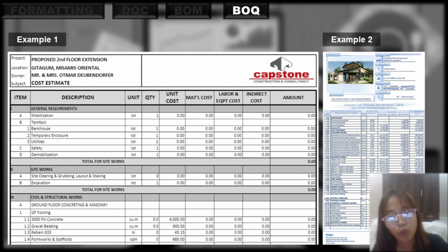The Bill of Quantities or BOQ is a document that contains information on the quantity of materials, labor, and their cost in a construction project, while BOM is related to the list of inventory of raw materials, parts, and components. BOQ is like BOM, but it involves costing of labor too, and other indirect costs now. The basic elements are project name, owner, project cost, number of calendar days, description, table of estimate with summed up materials, labor, direct and indirect costings.